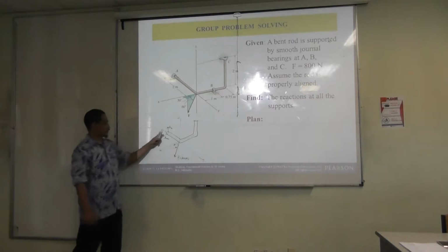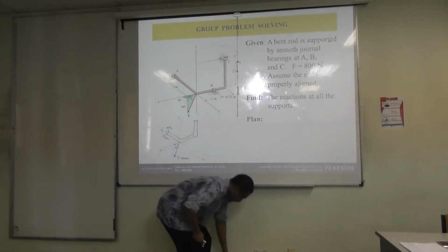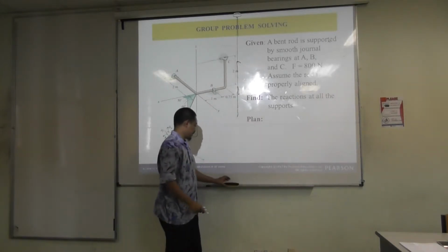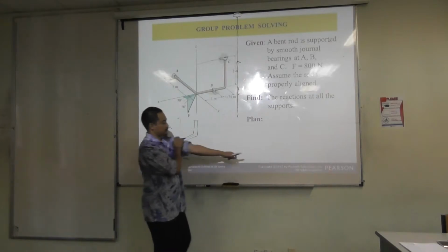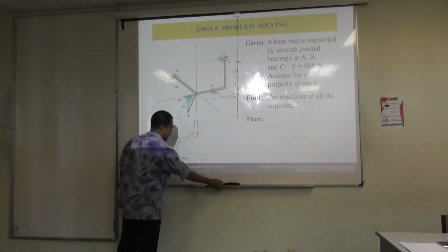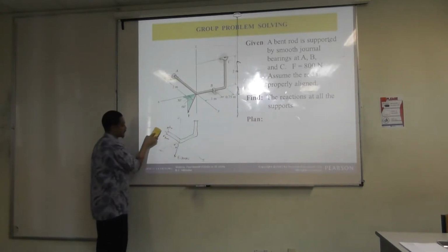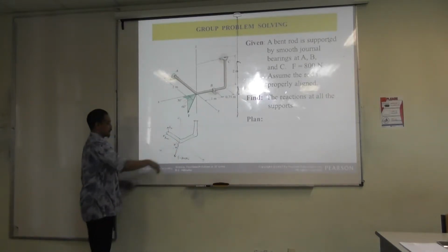Now, how do you determine whether you have AY or not? Yeah, that depends on the name, right? So we have truss bearing and general bearing, right? So for general bearing, do you have AY or not? No AY. Why? Because it does not restrict that movement, right? You are actually free to move in that direction, right?